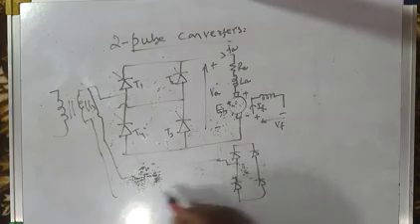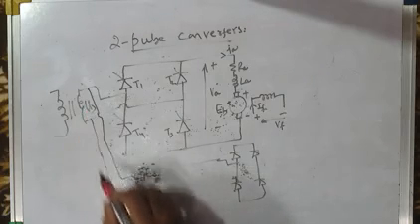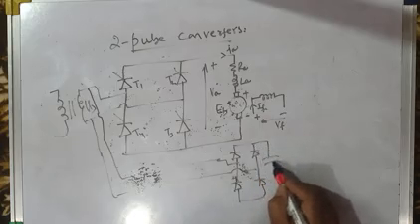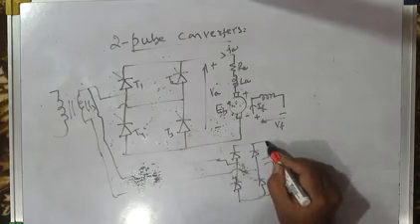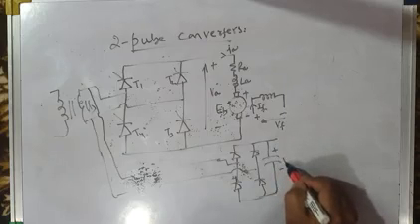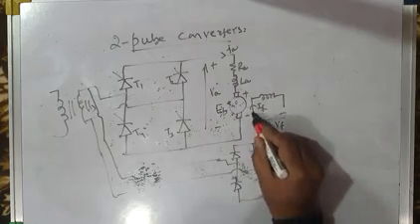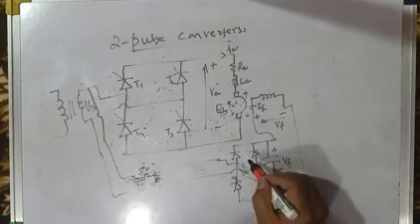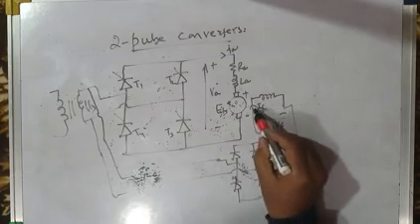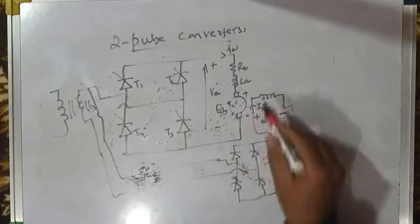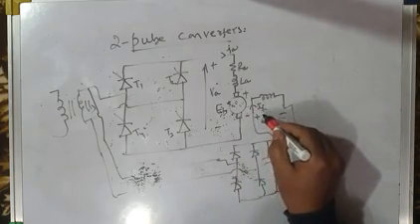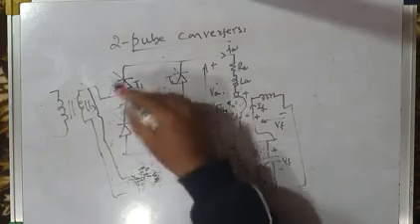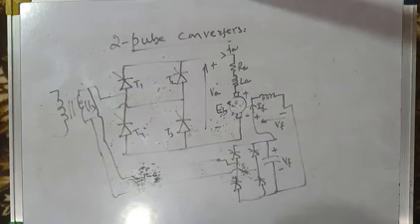The input to this rectifier is this transformer output AC voltage, and what this rectifier does, it converts this AC voltage into DC voltage, and this is the field voltage VF, and it is fed to the field winding. So field winding is fed by a bridge rectifier, uncontrolled rectifier, if you need constant field current. But if you want to change the field flux also, then this bridge rectifier may be replaced by phase controlled converter, just like armature converter is a phase controlled converter.